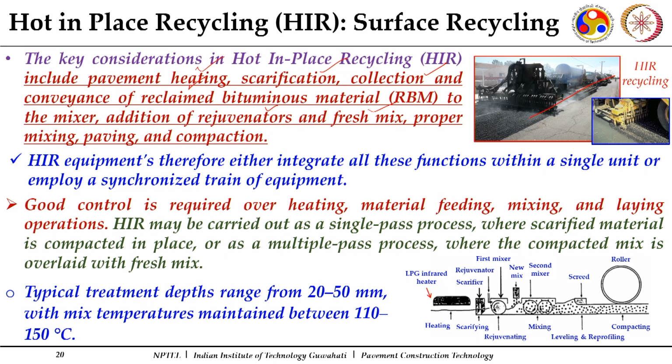So hot in place recycling equipment can either integrate all these functions within a single unit, or employ a synchronized train of equipment. One unit is doing the heating, the second unit is doing the scarifying, the third unit is doing the mixing, and the fourth unit is giving you the mix through the paver and the screed, and finally the rolling and compaction.